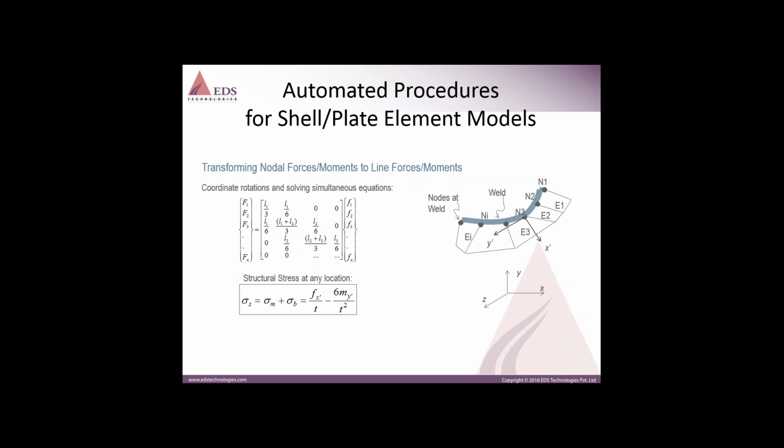So this is the way that works. There's a schematic of a weld line on the right hand side where you can see a big black line showing the weld curving, dots at the nodes and the grid lines of the elements. A local coordinate system is generated at the start node and transformed along the weld line as it is a curvy structure.